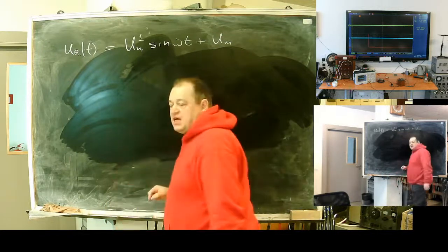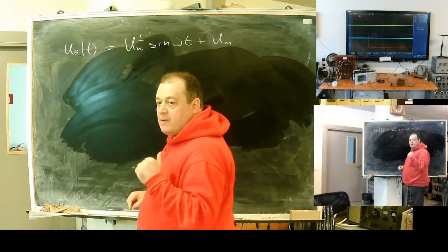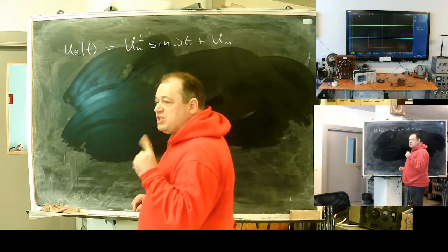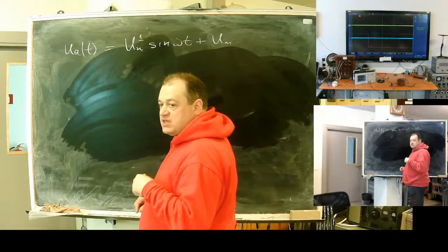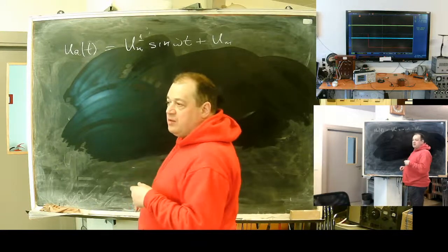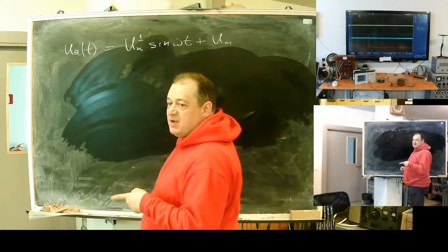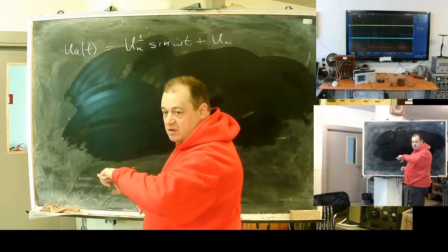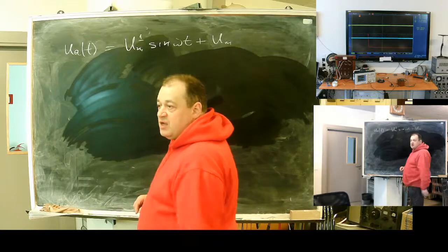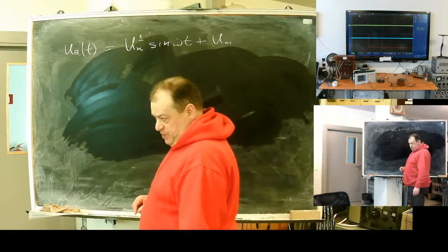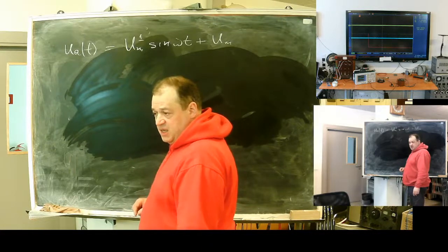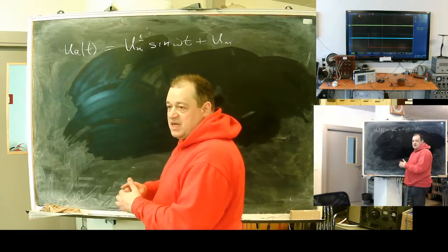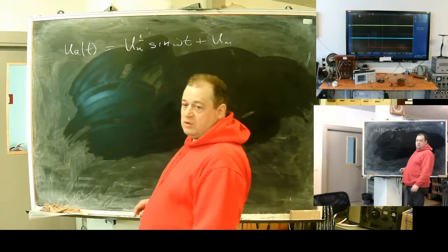Can it have a second harmonic? No. In stationary regime, no, only during the transients. Why? Because we have a symmetry here. After half a period, the rotor turns, so we have a symmetry, meaning what? There will be no second, fourth, eighth, and so on even harmonics.